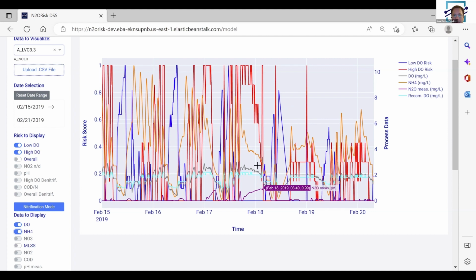So now you're still converting ammonia, obviously, because you have to, but now you're doing it under lower risk. You can see the risk is way down here, where before it was way up here. So now, because we've been able to reduce that, we've been able to knock down the N2O. So you can convert ammonia at lower risk and not produce as much N2O, almost eliminate it.